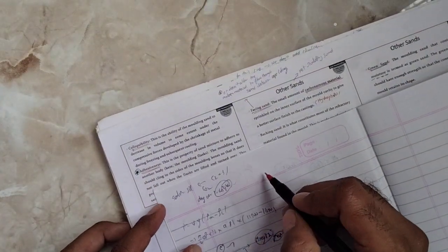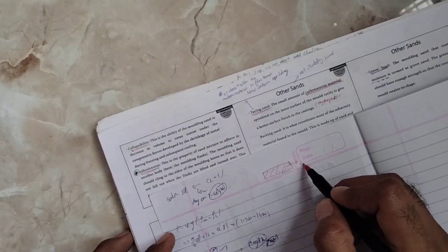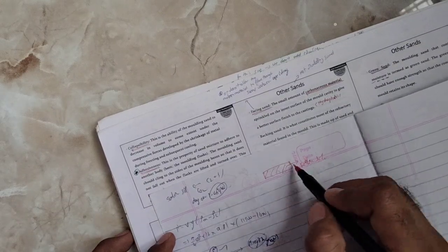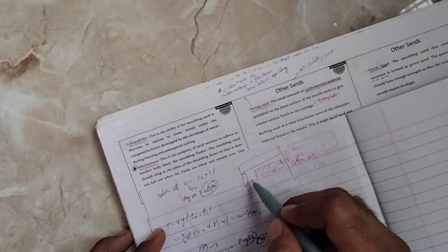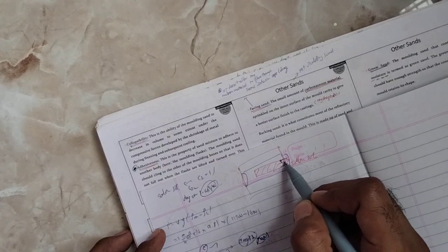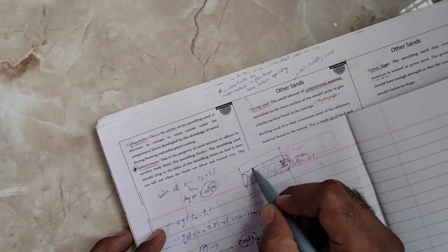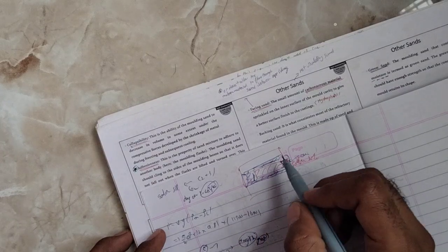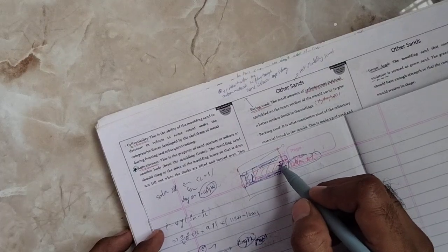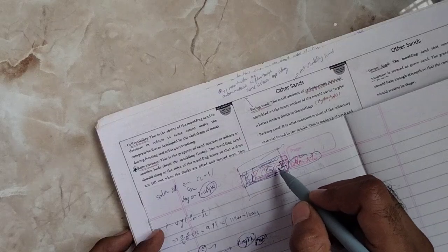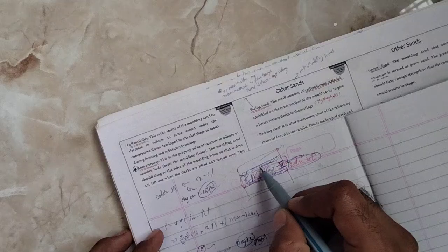because collapsibility is the most important thing. For example, this is a core. The core sand, for example, is made up of sodium silicate. Whenever we pass CO2 like this, we need a cylinder like this. So this is a molding sand base and we just pass the CO2. So the aluminum metal goes and passes over this and it's fixed in a good shape. But the main issue is this is a core sand made of sodium silicate. Now we have passed carbon dioxide here. So the sodium silicate and carbon dioxide make it get so much harder. So it doesn't compress, it doesn't shrink.